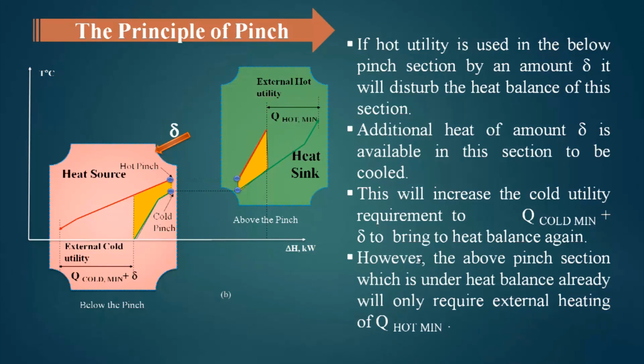However, the above pinch section, which is already under heat balance, will only require external heating of Q hot minimum. The overall hot utility will increase, but if I only see the above pinch area, the hot utility amount will not increase.